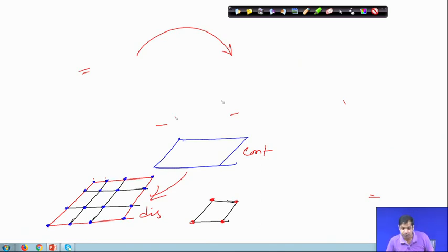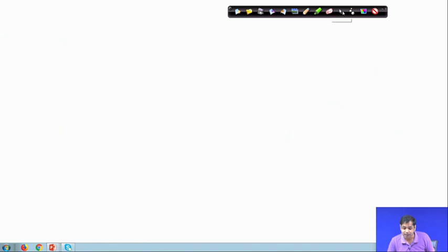When you have a finite number of points, what are we essentially doing? We are reducing the degrees of freedom, right. So, every point has 3 degrees of freedom, 16 points, 48 degrees of freedom. But the actual system has infinite degrees of freedom. When you discretize it, we are allowing only 48 degrees of freedom. When we reduce the degrees of freedom, what are we doing?